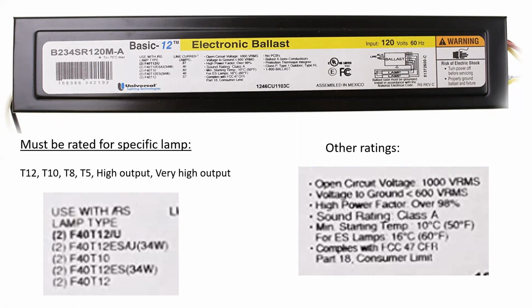It's always important when you're relamping live lighting fixtures that you don't touch the end electrodes as you're inserting the tube, because one end of the tube could be inserted and the other end could be your finger across them, and 1,000 volts feels very tingly. So you don't want to have that happen. Voltage to ground, very high again. Power factor, sound rating.